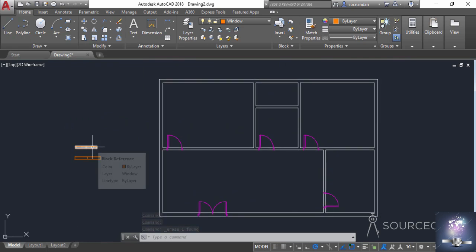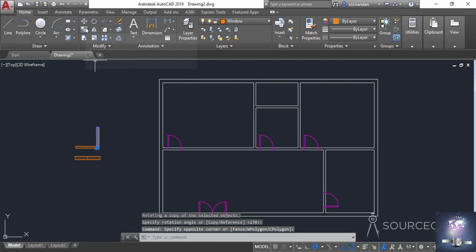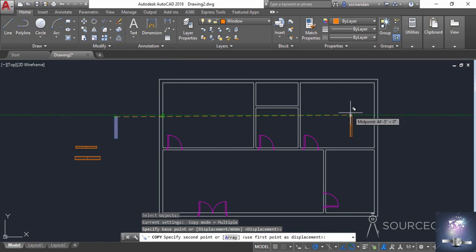I'll start by adding this window, but I'll make a copy of this and I'll first rotate this one. So select rotate and click on this point, and you can directly make a copy by rotating this also. So I'll simply click on copy and make another copy of this which is rotated to a particular angle. You can move it also, here it is. Now select the copy tool, select this one and move it on this wall. Obviously we need to move this second one, as this is the wall of 10-inch thickness, so we can move it inside this drawing, and here in this case we will place it on this wall just like this